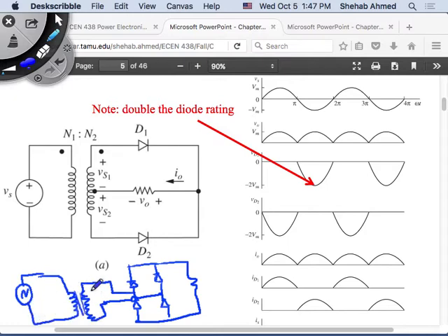And then you have a nice system where you're stepping down your voltage with a ratio of n from V to V over n, and then you can convert that to DC and put your capacitor here to reduce ripples, right? This is a very common circuit in electronics. So this is nice. You can do that with the previous circuit.